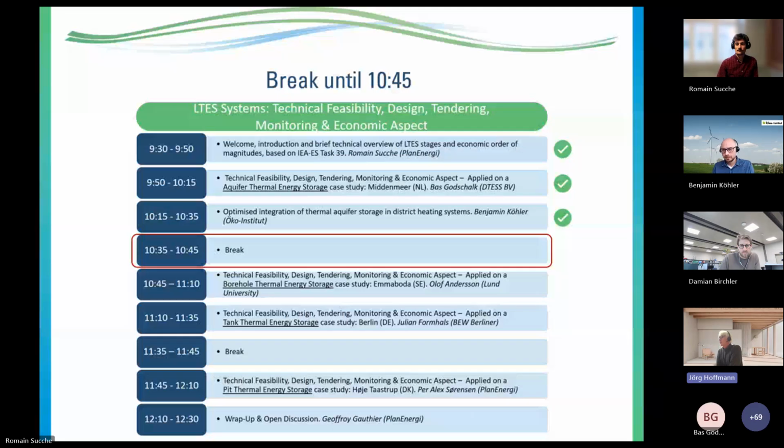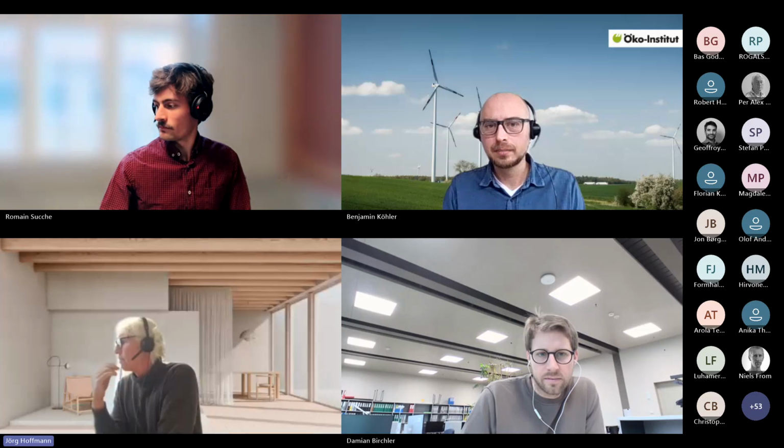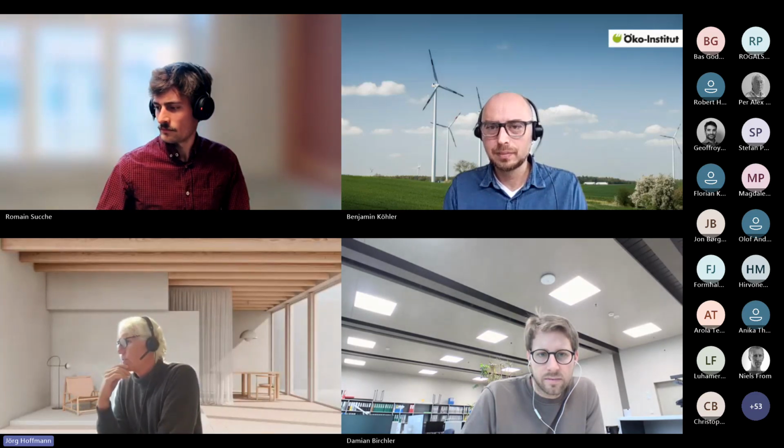I'm here. What I see in Switzerland now is that we have more capability to use environmental heat sources like the lakes. We see a change in the district heating networks. We have high temperature, 170 degrees networks at the moment in some of the larger cities, but they are slowly coming down. They're changing to 120 and even lower if possible. Did you notice a similar effort at the district heatings you observed?